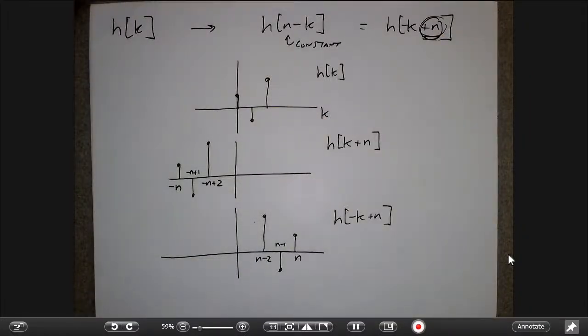When we have an impulse response that will have an effect before the signal starts, does it still apply, will we still use the same thing? Right, so the question is, can we still use the same thing when there's an impulse response beyond 0 on the left-hand side? So if I have negative values, like h of -1, h of -2, the answer is yes, the same idea applies.